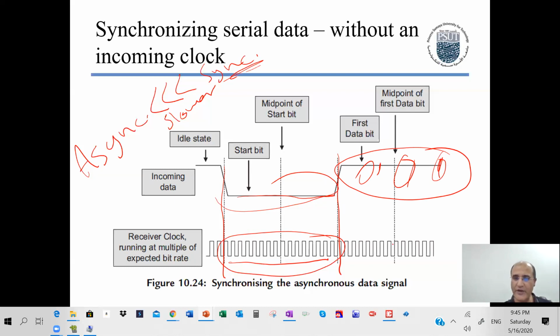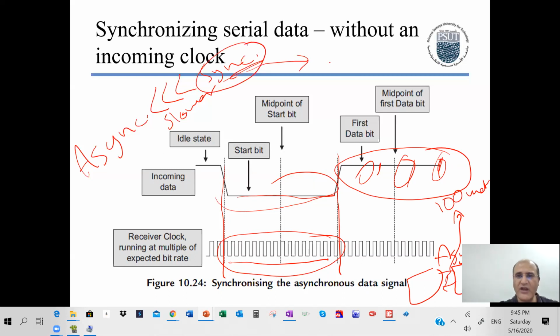So it's much slower, but it saves resources, right? And usually, because you're not sending a clock between the 2 devices, you can connect 2 devices in asynchronous mode, and this line could go up to 100 meters. While in synchronous, we're talking about centimeters, a meter maximum, because after a certain length the clock starts losing synchronization. You cannot keep sending at that very high speed. Okay.